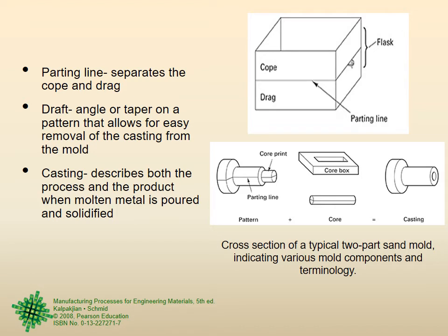Parting line, you know, right? Again, we are showing the cope and the drag and the whole flask, and this center line above and below which is the cope and the drag is the parting line. Then draft is something new. Draft: angle or taper on a pattern that allows for easy removal of the casting from the mold.